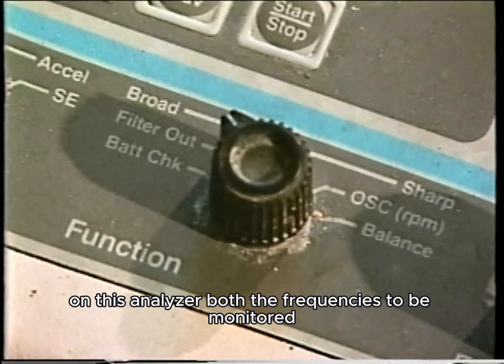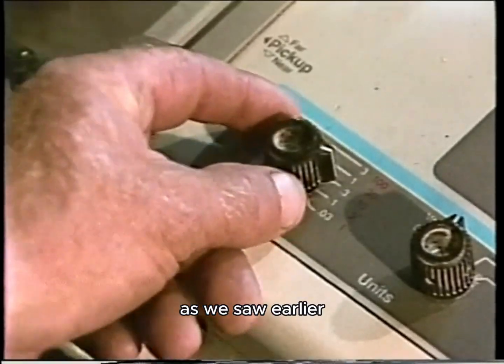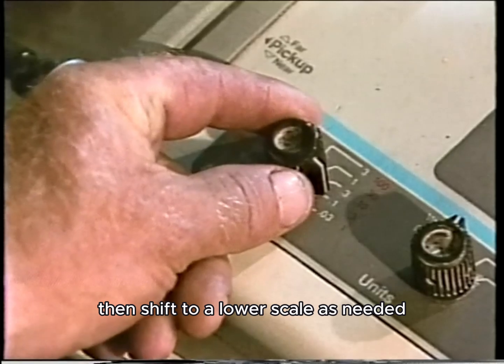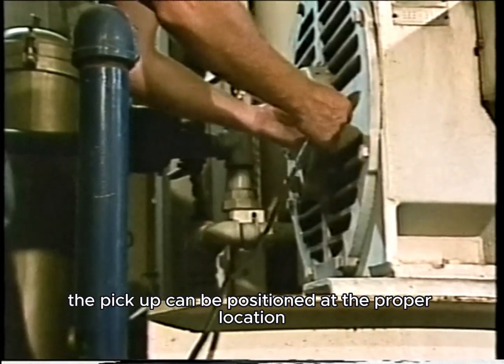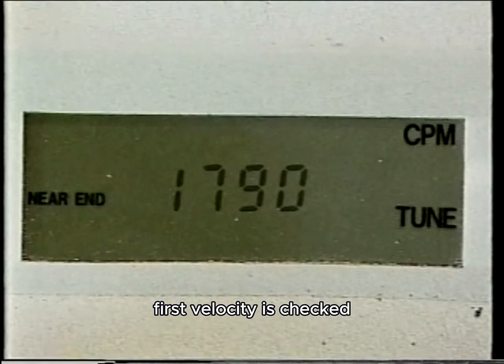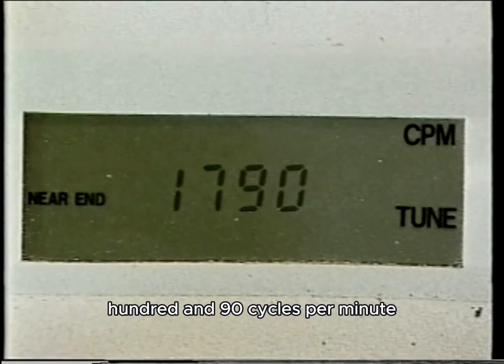On this analyzer, both the frequencies to be monitored and the scales for the indicator can be selected. As we saw earlier, it's a good idea to choose the highest indicator scale, then shift to a lower scale as needed. Once the settings have been chosen, the pickup can be positioned at the proper location, and the data can be collected. First, velocity is checked. Here, the analyzer meter shows a peak at a frequency of 1,790 cycles per minute.